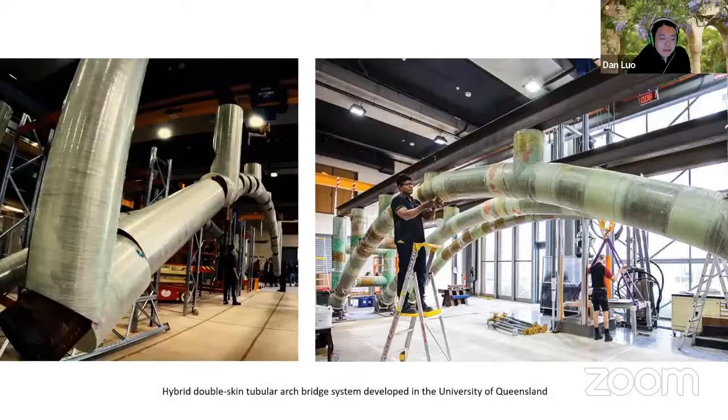A significant benefit to this is that this is an existing building brick prototype that was developed at UQ. So the idea is that we're able to use those fabricated FRP tubes to construct, let's say, large-scale bridge structures in remote areas. The benefit of using these tubes is that they are very lightweight. They are industrially fabricated. You can connect them with manual labor instead of requiring advanced machinery that is difficult to transport and expensive to use.